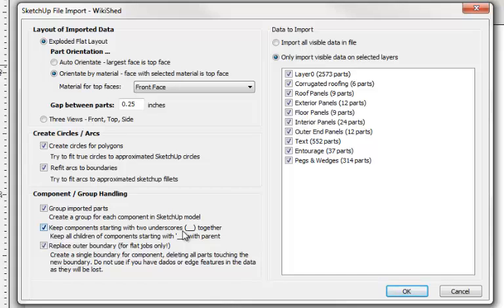By adopting this naming convention for our components in the SketchUp model, we can tell VCarve Pro to stop taking the component apart to that level we saw. Once we reach one with a name starting with double underscore, we know that that should be treated as a single component. And this is another very important option for this sort of construction.